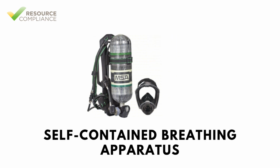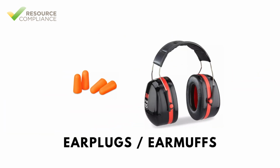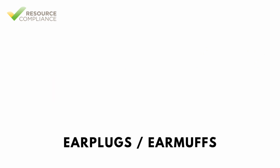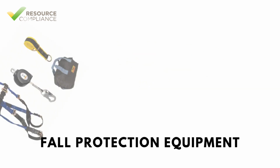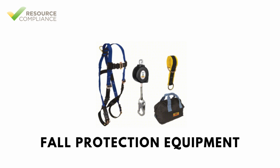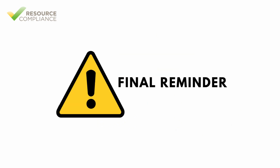or oxygen deficiency. Earplugs or earmuffs are required for high-noise areas, such as machinery rooms. Arc-rated clothing is necessary for electrical work with potential arc flash hazards, including arc-rated face shields and balaclavas. Fall protection equipment, including harnesses, lanyards, and anchors, is required when working at heights on platforms, rooftops, or ladder access equipment. PPE selection must be task-specific, properly fitted, regularly inspected, and used in conjunction with safe work practices. For refrigeration technicians, PPE is the last line of defense, not a substitute for hazard elimination or engineering controls.